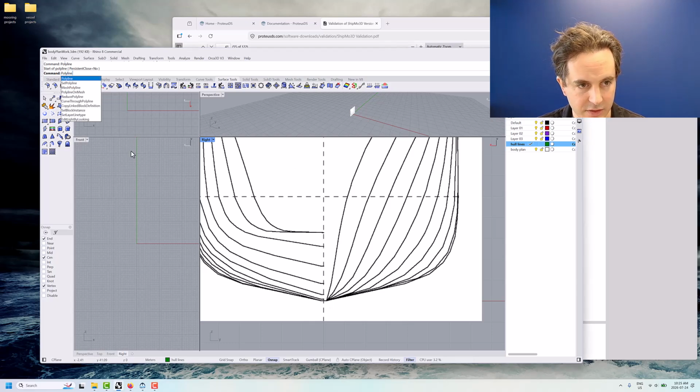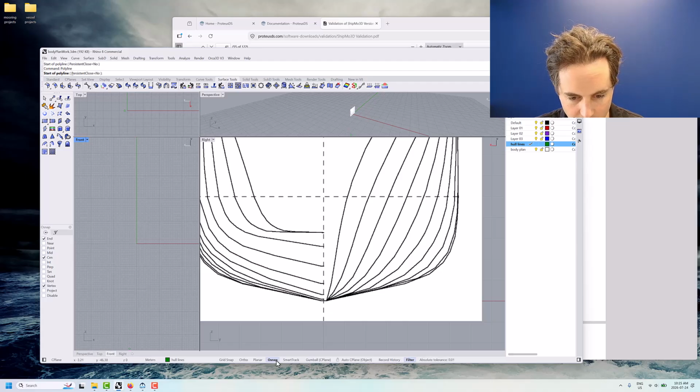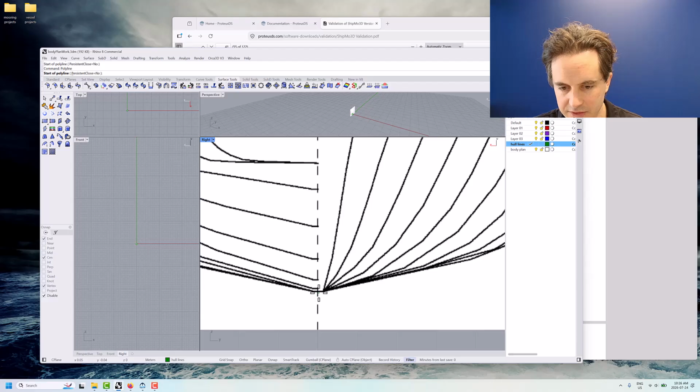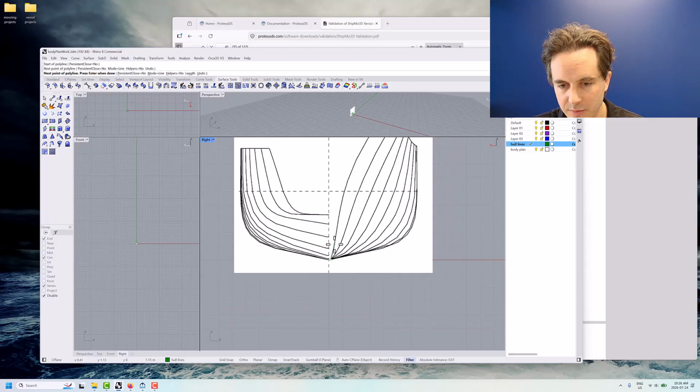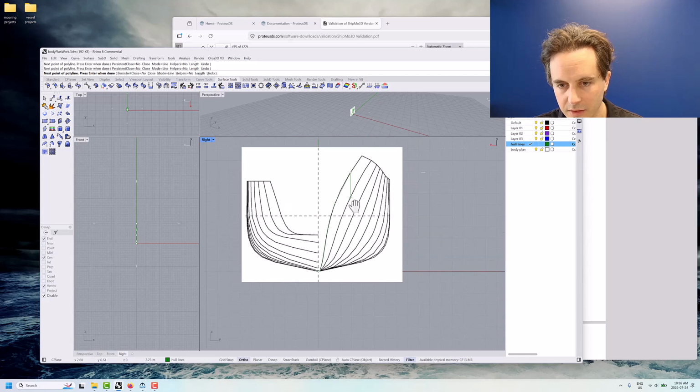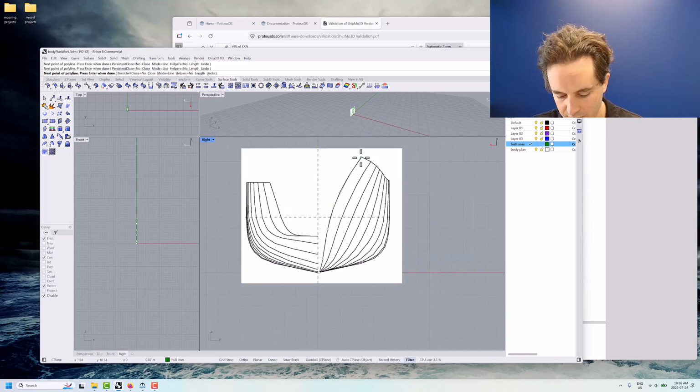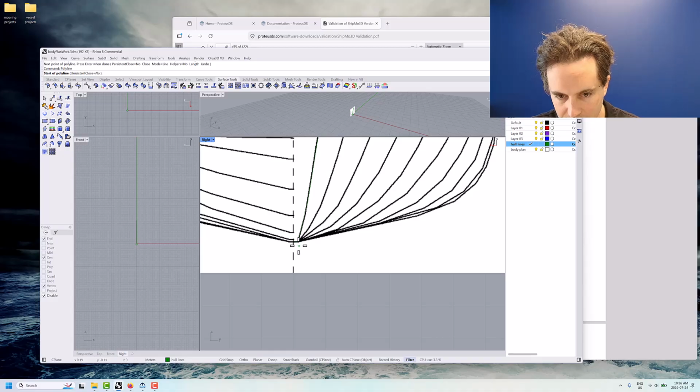And I might suggest you also turn off O-snap. We just don't want the lines snapping on each other, and it's kind of irritating when it does that. So I'm going to get it kind of close to the center line and baseline. It doesn't have to be perfect, but we'll start with the front shape here. Again, you can spend the time you want to get the resolution you want. Go there. And the whole thing here. That's one hull line. We'll do it again.